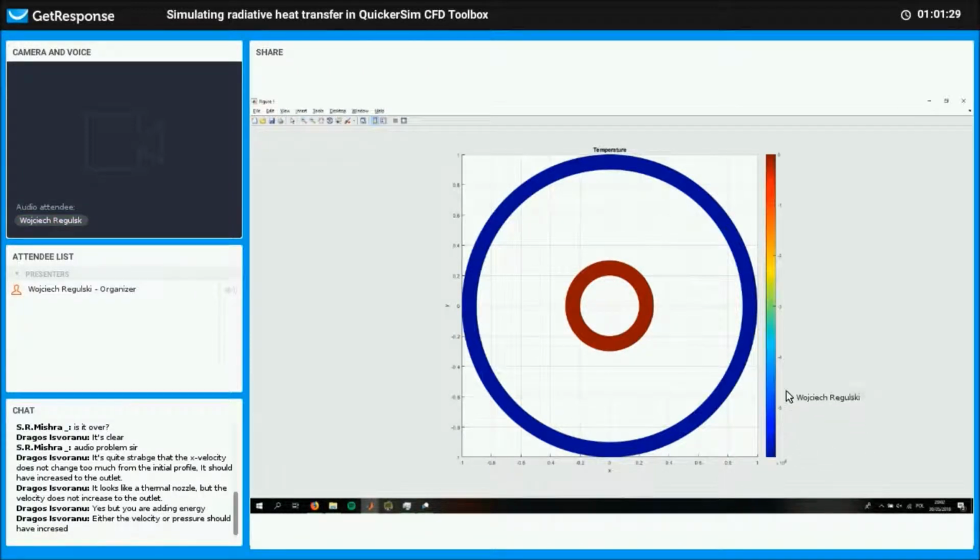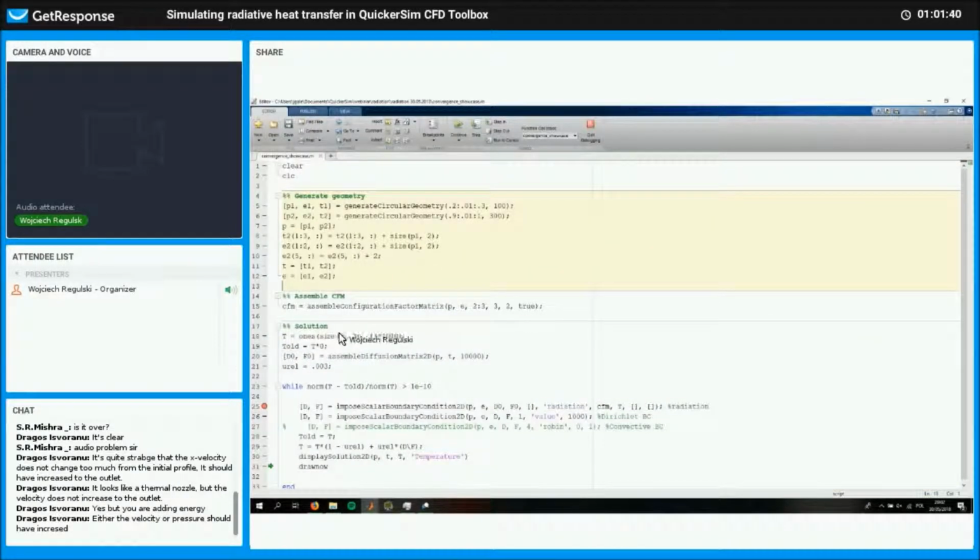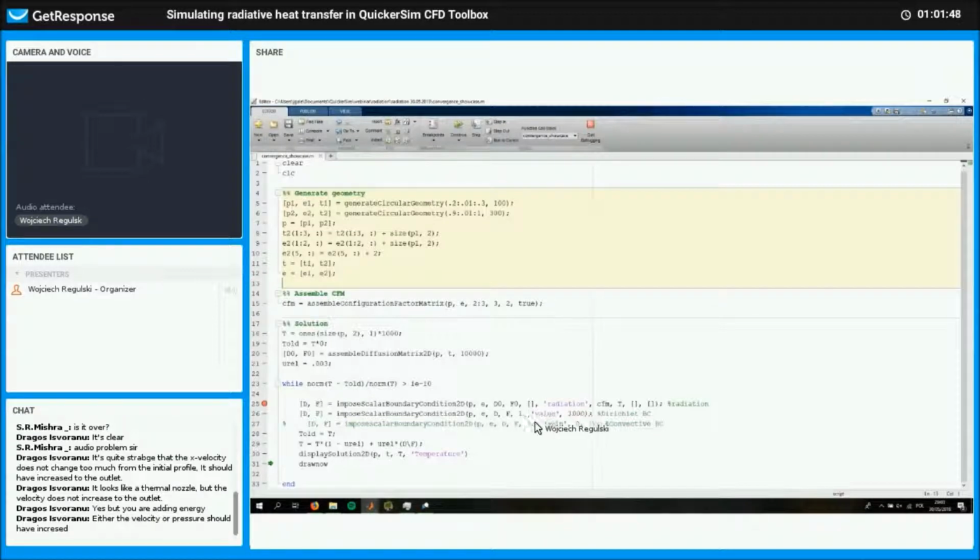Apparently the numerical error in the heat flux was negative. So our simulation blows up instantly, even, as I said, with a very, very small under relaxation factor. So the solution is actually only a small fraction of what it would be without it.